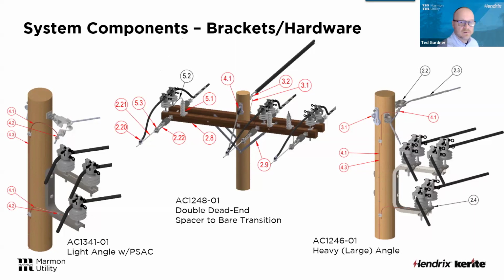And one of our rules of thumb is anytime we remove the covering, whether it's for a tap or a transition pole or anything like that, we recommend installing lightning arresters.